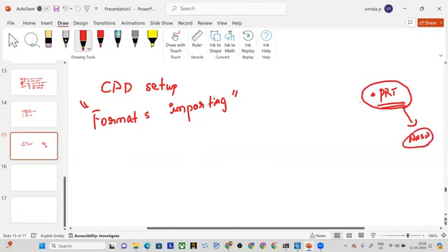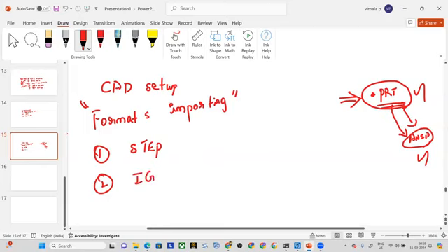it will not open, because this works under a different graphic standard, whereas this CAE software works under a different graphic standard. So if you want your component to export to ANSA and open it without any problem and work on it, then you have to follow these generic CAD formats. One such basic format is STEP, which is very popular. Whenever you are doing component modeling using SolidWorks, Creo, or CATIA software, you are going to save that file in this format, STEP or IGES